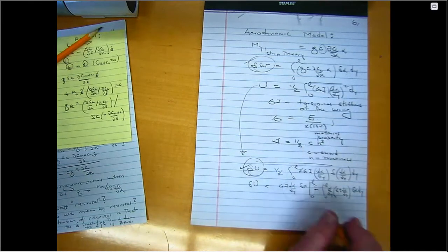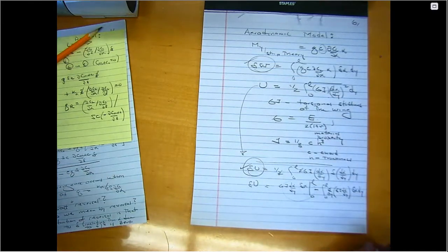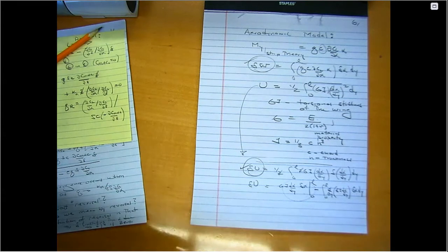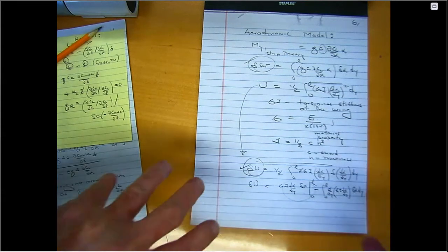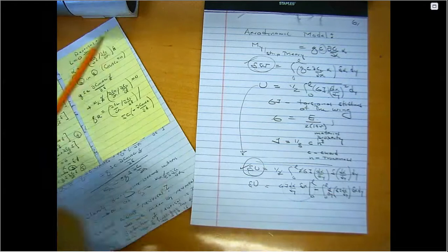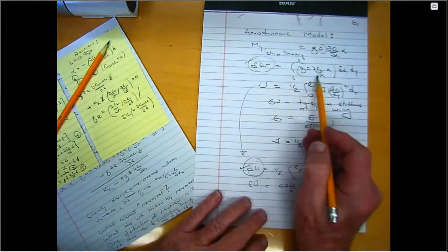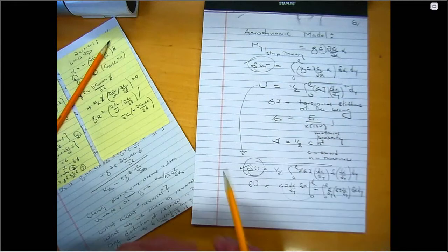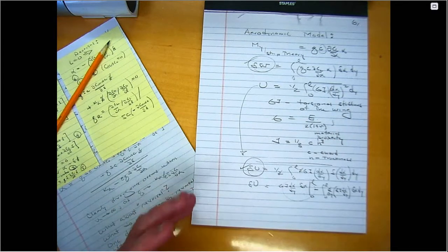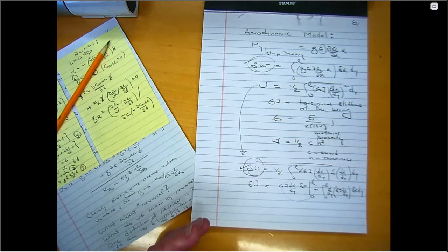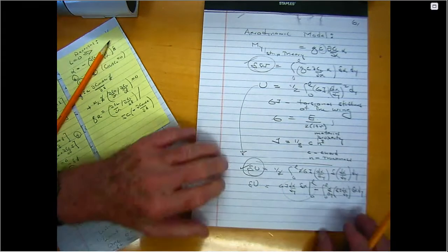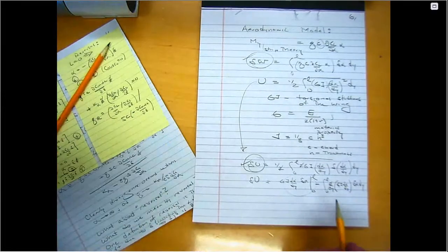Because there are occasions known in the literature, famous examples, where people use the wrong combination of equation of motion, in this case equation of equilibrium, and the boundary conditions. This method ensures that you are at least consistent. Once you write down potential energy and virtual work, it's just a matter of following the mathematical stages, and you're guaranteed, assuming you do the algebra, you get the right answer. Okay, so let's put this all together.